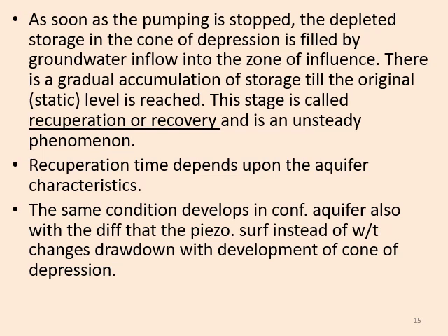When the pumping is stopped, the depleted storage, meaning the water which is decreased from the storage, which we have taken out by pumping in the cone of depression area, is filled by the groundwater inflow from the area of influence. So there is a gradual accumulation of storage till the original static level is reached.